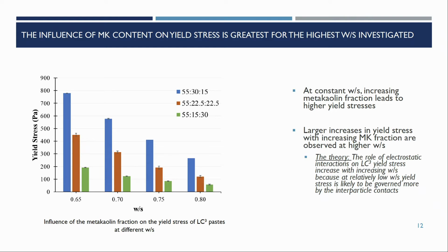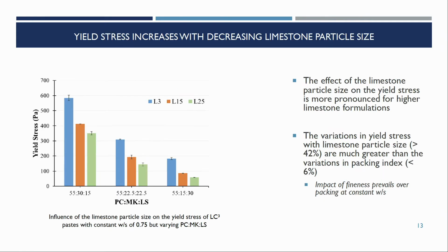We interpreted that as meaning that as we are forcing the particles to be closer together, potential electrostatic interactions, again coming from the zeta potential of the clay particles, are coming through and tuning some of these. So it's not like we're immune to zeta potential effects, but the basic trends are still dominated by water and how much of which one.